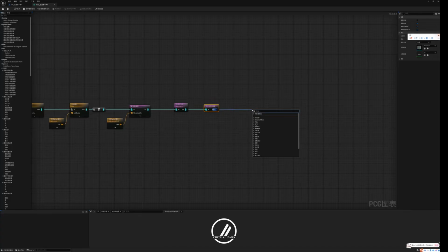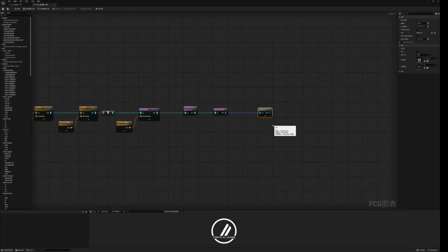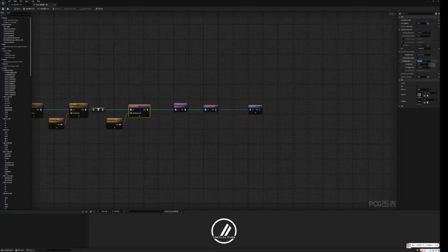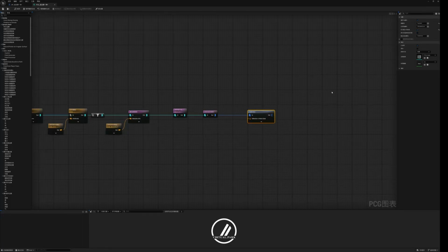The third one is the select syntax node. This node is used to control the conditions for generating the model along the spline. Change the key attribute here to the name of the symbol attribute in the duplicate cross-section node. In order to write the rules using variables, check the option for the standard that serves as the input. Then connect the variable.